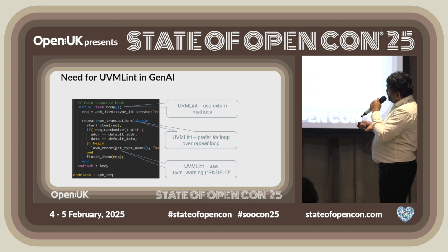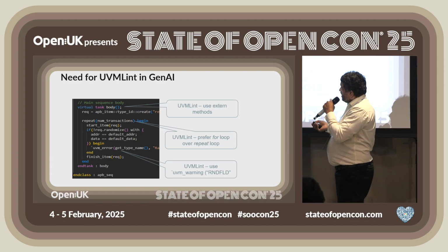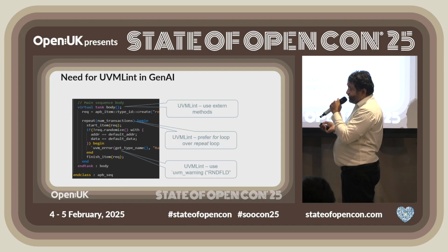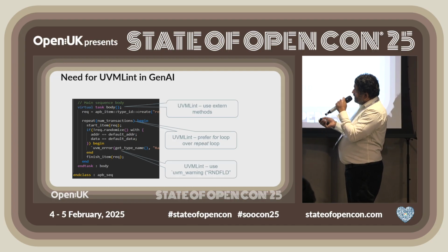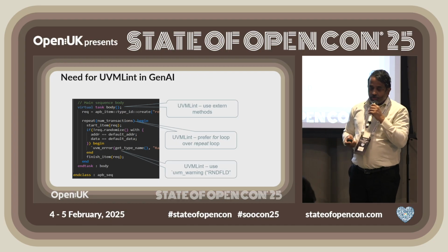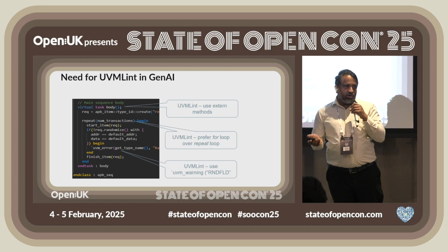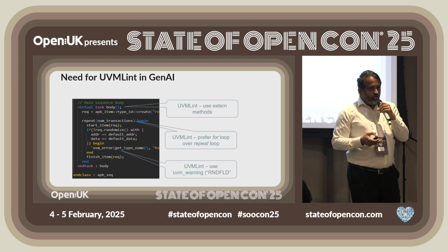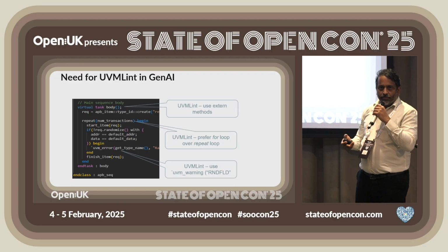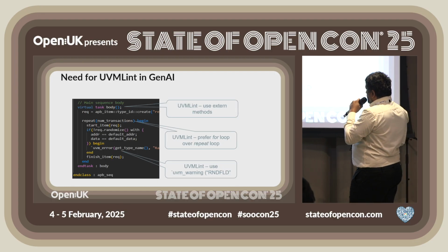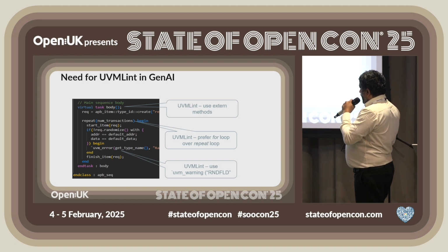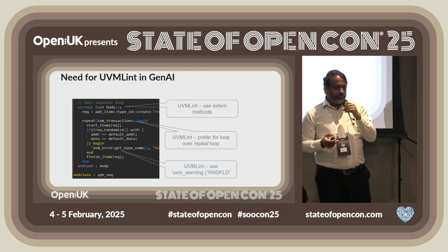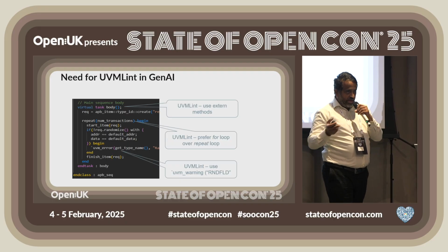Next, a quick one. This is a very specific UVM rule, wherein if there is a constrained random generation failure, if for whatever reason the address could not be constrained to the address that you wanted, throw an error, which is fair enough. However, the UVM library, the IEEE core library, uses a specific API called uvm_warning with the ID RNDFLD, which I believe stands for randomization failed.